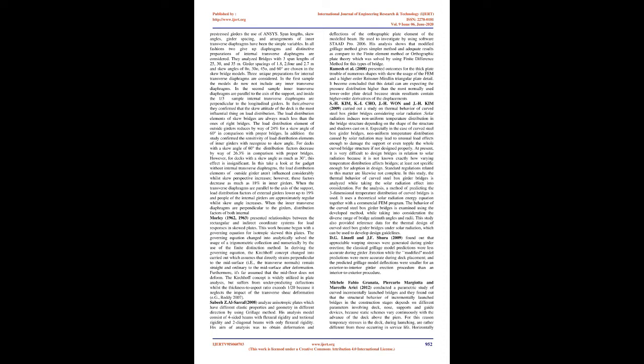Specifically, an increase in bending moment and the existence of a torsional moment in cases where the horizontal angle of curvature is large, about 20-30 degrees, was observed. The significance of these moments, compared with the maximum bending moment of a comparable straight bridge, was noted.